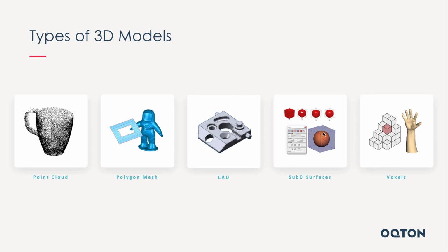Now, two other ones that I'll cover really fast. Subdivisional surfaces. These are a surface type that's used a lot in animation and the AR VR world. Different types of representation in the world. What these are very good at is push-pull modeling. Subdivisional surface models is what you'll hear them called. They're kind of like a hybrid in a way. I think of them as having a NURB surface that's controlled by a polygon outer armature or frame that helps pull and push and create shapes. Again, used in AR, VR, and animation.